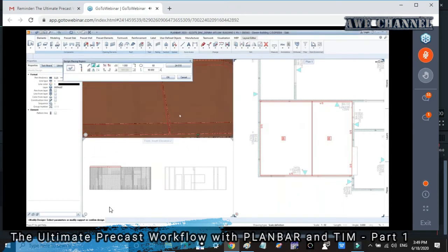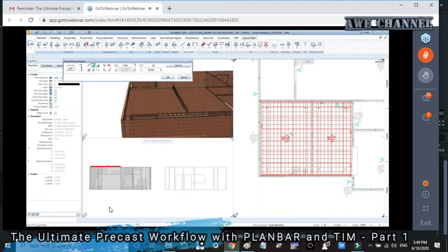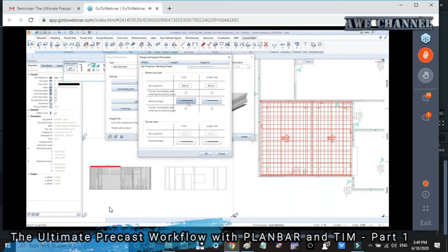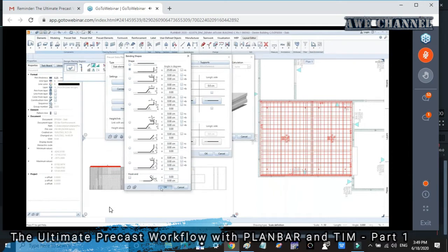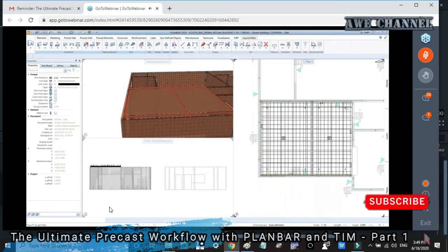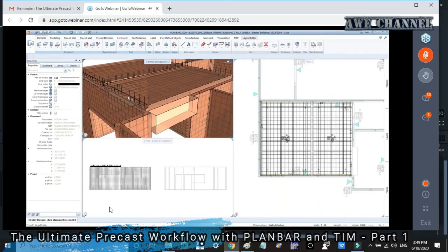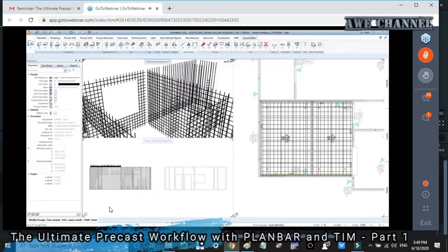And when you ask about end connection on the left and on the right, and on the longitudinal side, you can also have it. I just go to design again, and from the design I have to go to bar projection. From the bar projection, I just load the setting for the bar connection, and then I say OK. Now you can get bar connection at the end phase, or from the start to the end.